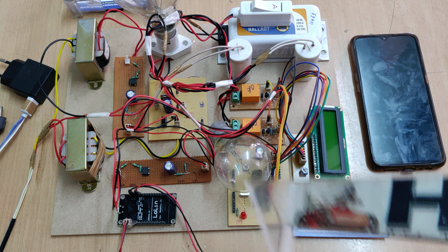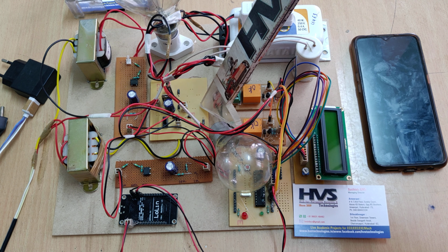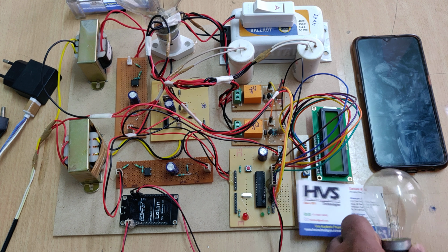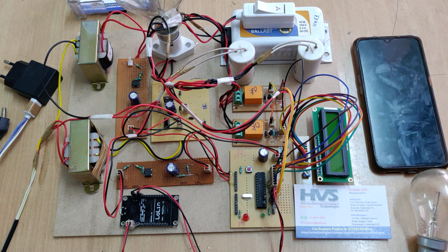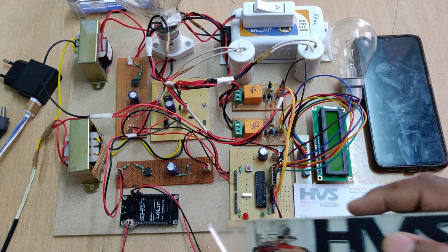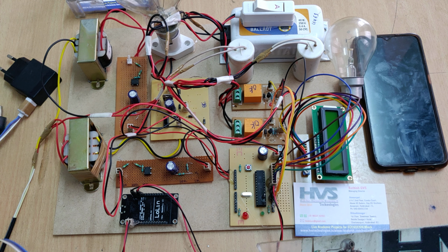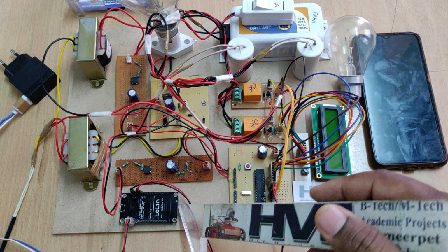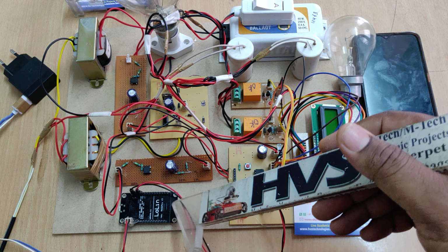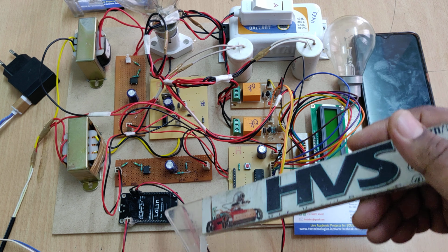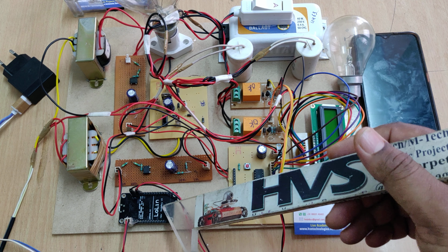circuits to detect the zero crossing of current transformer and voltage transformer, and this one is the regulated power supply board in order to provide the 5 volts power supply to the motherboard of PIC microcontroller and 12 volts power supply to these relays, because we are using electromagnetic relays which can operate at 12 volts. And now we are going to provide an extra power source for the node MCU, because it needs more power. It will upload the power factor value to the Blynk app, which is already stored with the authentication API key inside this node MCU.